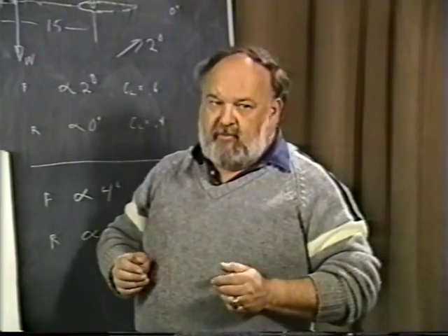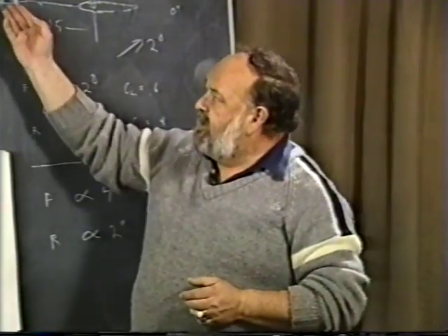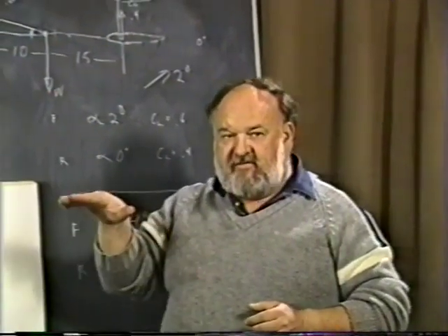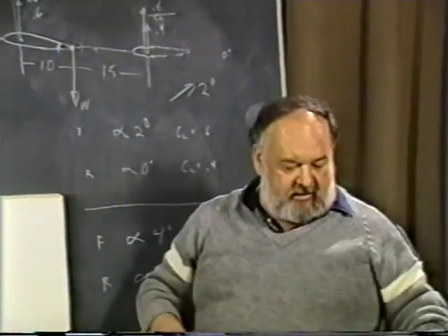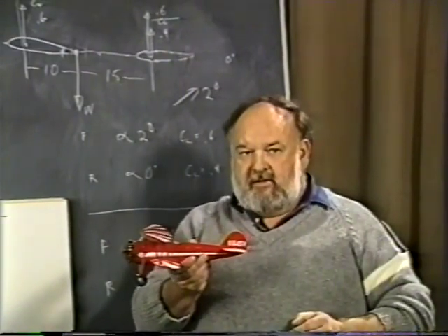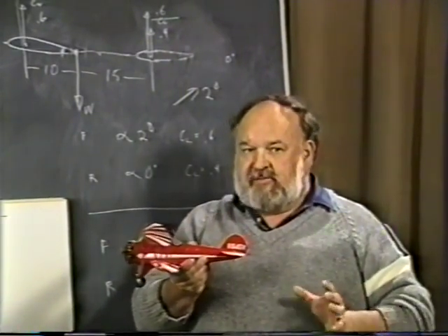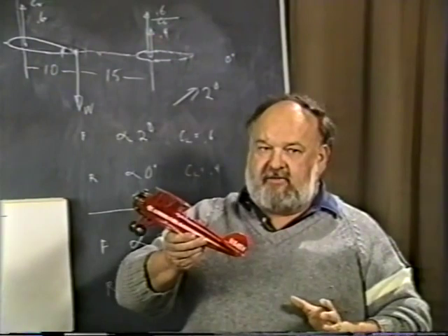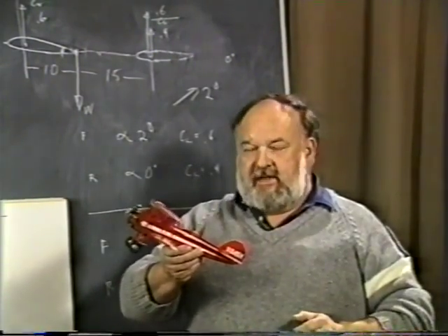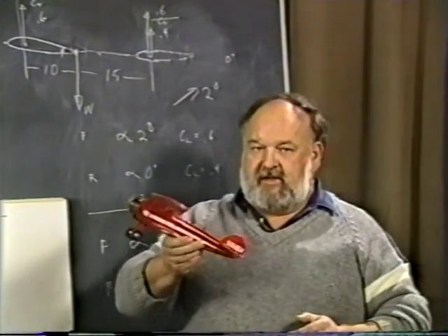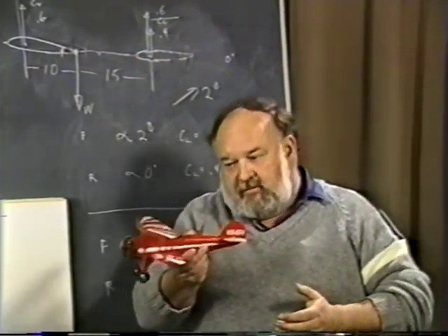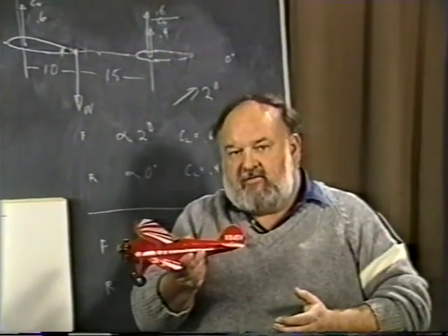In fact, on most airplanes, because of the camber of the wing, you actually have a download on the tail. The airplane is flying along, the wing is lifting, but the tail itself is producing a slight download. This is perfectly acceptable and perfectly good, because when you get an increase in angle of attack, if you hit a gust like this, the download will reduce itself to where it has to change and pitch back over again.